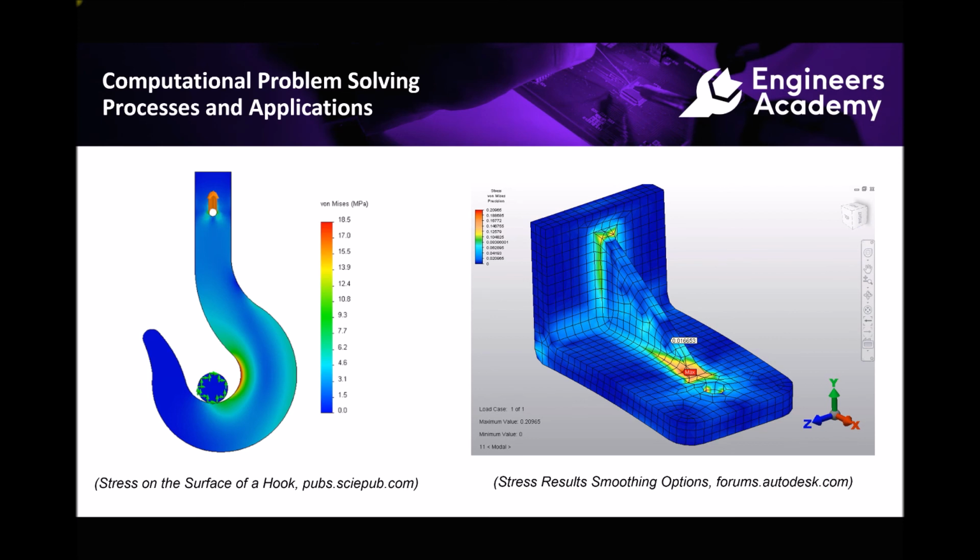So what the software does is it continues to do this trial and error process until we get something called convergence. Now convergence is when on subsequent iterations the results from the previous iteration and the new iteration are almost identical. Once we get to that point, we know that we're getting very close to the final solution. So first iteration provides a rough approximation, second iteration is more accurate, third more accurate, and so on, and the software is going to look until two subsequent iterations have results that are almost identical, and then we know that we've achieved the final solution. That's what we mean by the iteration process and convergence in our calculations.